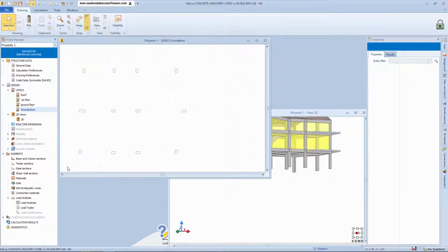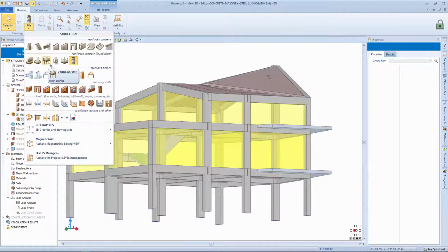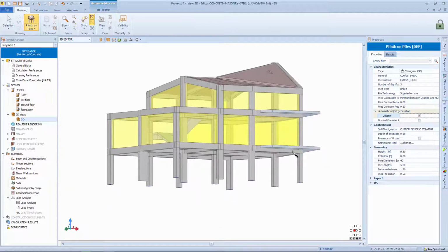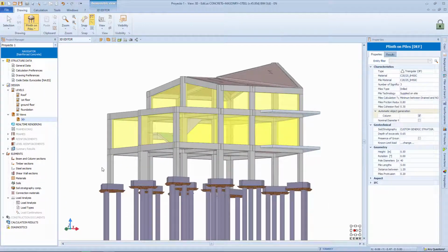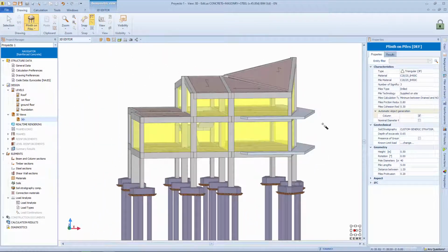It is also possible to model another type of foundations on poles, such as Winkler beams with poles or even footings on poles, which we can already find as a parametric object in the Design menu. We can choose within a fairly large file different types of footings with poles, assign a stratigraphy, and see that we can use an automatic generation from pillars. Then through a simple selection, we model on each beam a footing with poles.